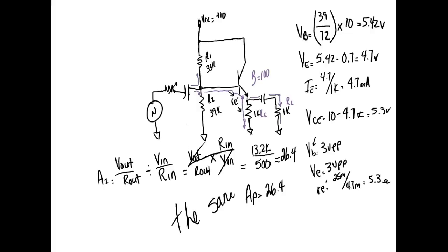It's going to go to 0, right? We'll have a little leakage current back through this guy right here, but it's going to be very, very low. We might measure in the millivolts there because we have that leakage current. This guy here is still reverse biased, right? You understand?